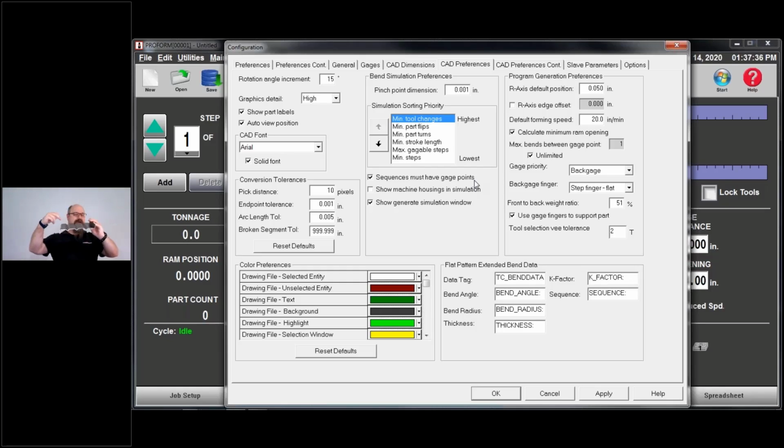So if I'm trying to make a bend, I don't want my gauge out here, I'm trying to see if I can, there we go, that's a better spot. I don't want to try to gauge out here if I'm trying to bend here. That thing's going to accordion across these other 6, 7 bends. I really don't want that accordion factor in there.